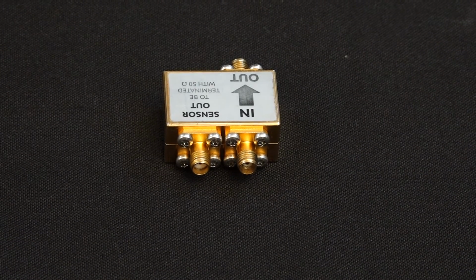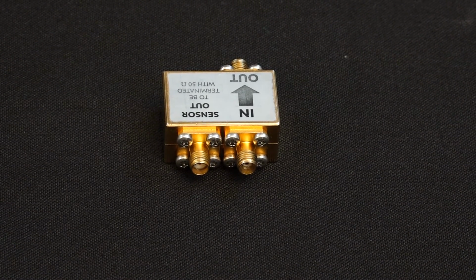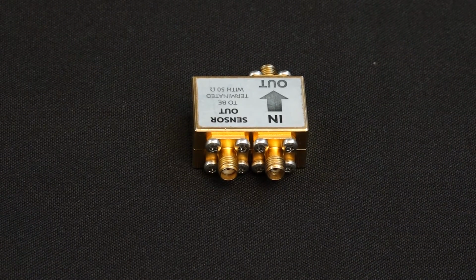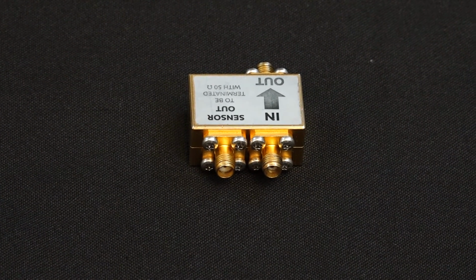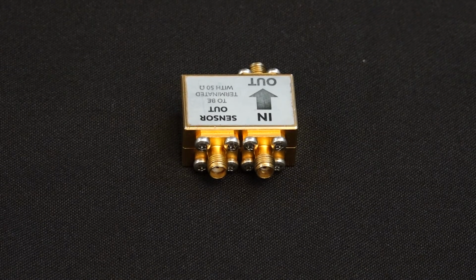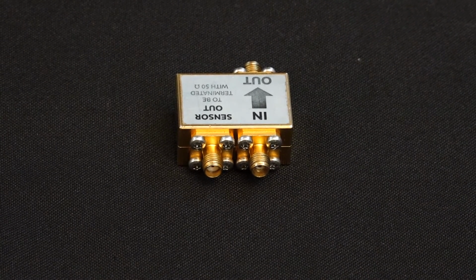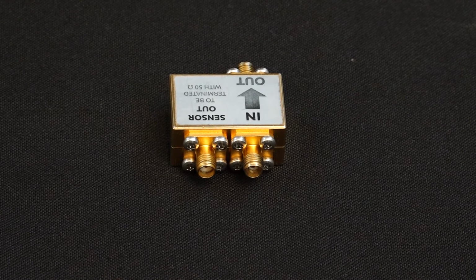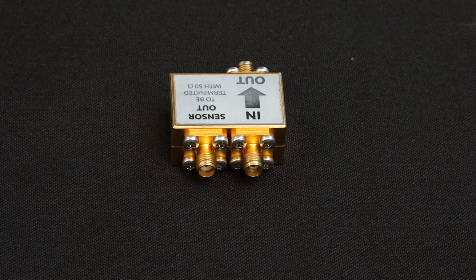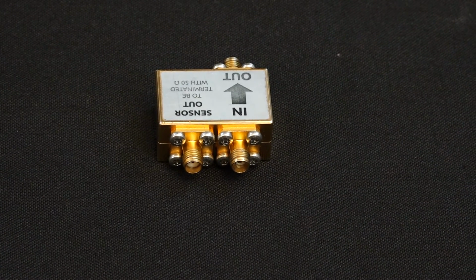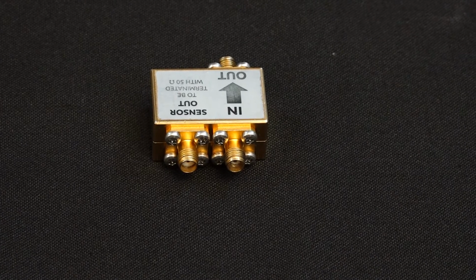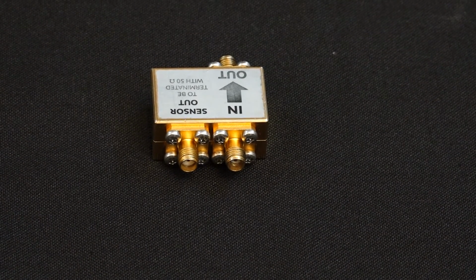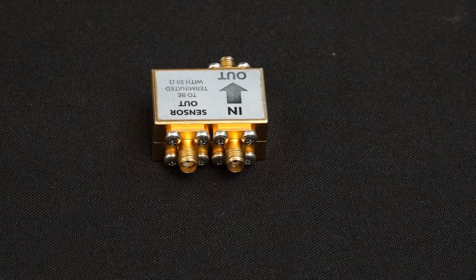We also have other current sensors which have a higher sensitivity. Say for example, another current sensor that we have has a sensitivity of 5 volts per ampere. That means it's a better current sensor in terms of measurement. That's because even your TLP setup has a lower limit for the current measurements. Say for example, if the device current is less than 100 microamperes, you would not be able to measure that using the whole setup. So the more sensitive your current sensor is, the better lower current measurements you will be able to do.